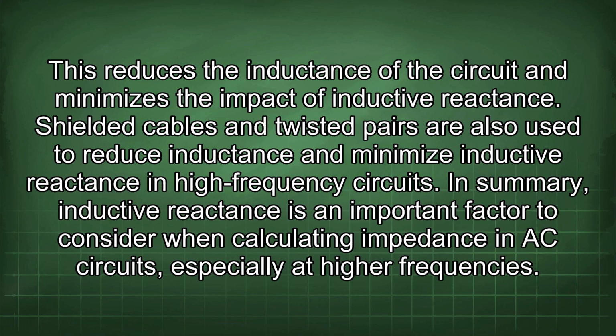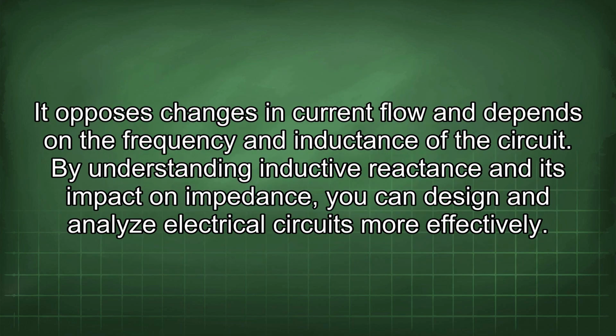In summary, inductive reactance is an important factor to consider when calculating impedance in AC circuits, especially at higher frequencies. It opposes changes in current flow and depends on the frequency and inductance of the circuit. By understanding inductive reactance and its impact on impedance, you can design and analyze electrical circuits more effectively.